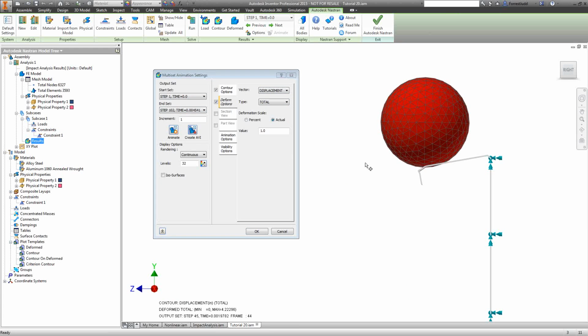Good question. Can you generate a mid-plane shell model in Inventor? Inventor Pro has a Find Thin Bodies tool that it can do. If you want to do shell models in Nastran, you have to draw the surface models yourself. That may be easy or difficult depending on what your model is like. If I'm creating something that I know I'm going to want to run a shell analysis on in Nastran, I'll start with that from the get-go. I'll create a shell, use that to optimize my design, and then from there I'll look at solidifying it into manufacturing geometry. And that workflow works really well, especially early on in a design iteration.